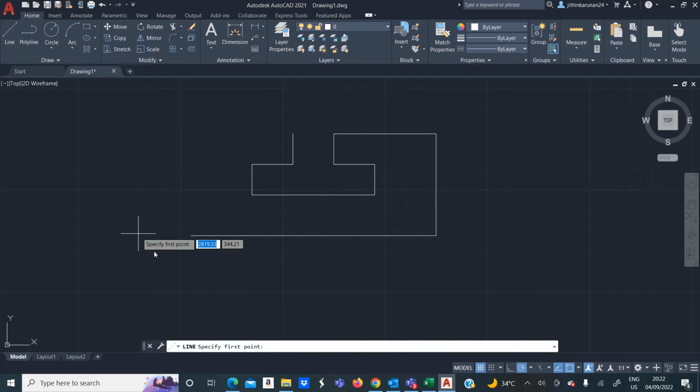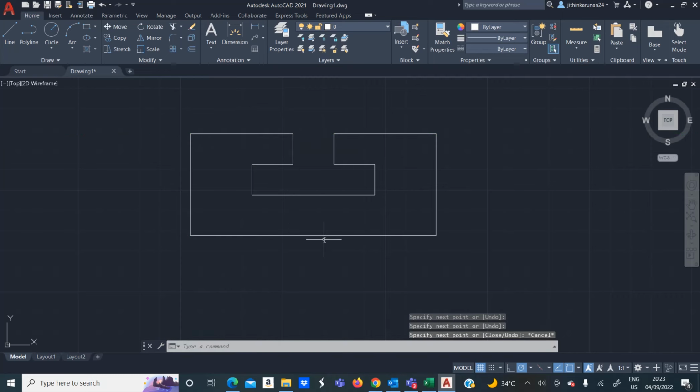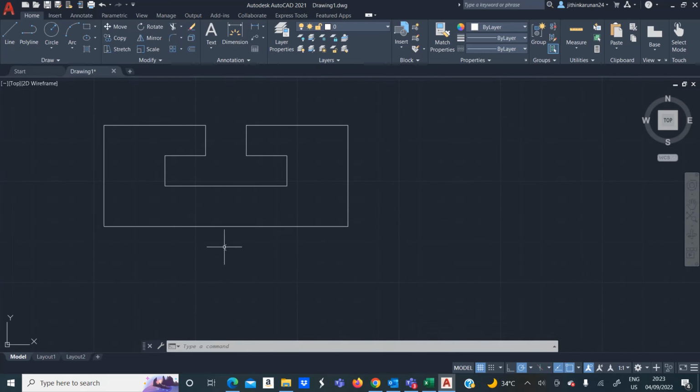So the easiest part is that either you can draw it with the dimension like this, or I'll show you, just select a line, click here, draw upwards, and we don't know where to draw it, the height. Just go to this point, don't click anywhere, and move it to the right, and it will give you the green. Once it is green on both sides, click there, then finally complete it. Thus our first drawing is complete, and now it is called dimension.